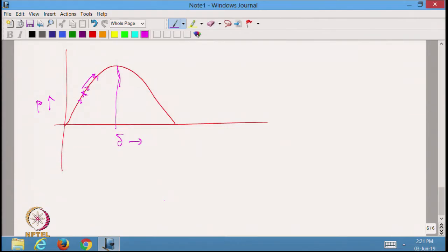Now, the angle delta is increasing further and further because 1500 minus 1490 RPM multiplied by t is delta, and as time progresses I am going to have an increase in delta further and further. If it has started from here and its 1 megawatt point is somewhere here, it will even overshoot that and reach a point where maybe it is generating 1.2 megawatt.